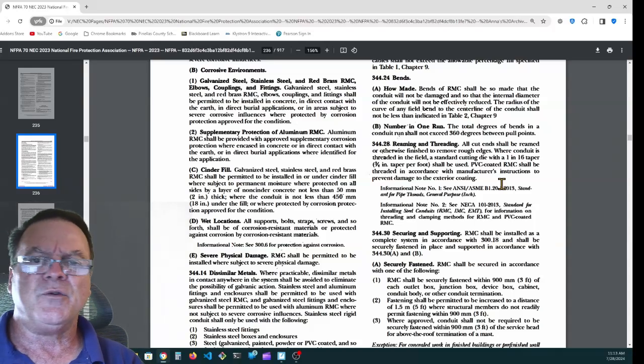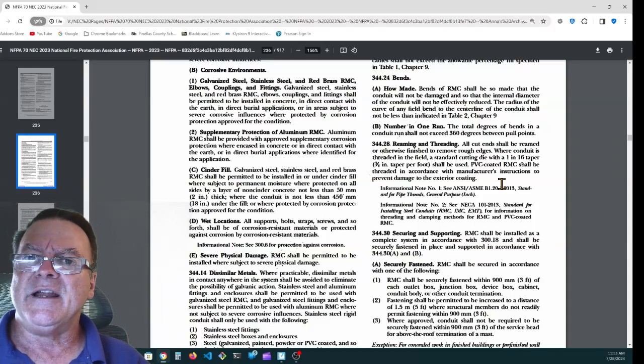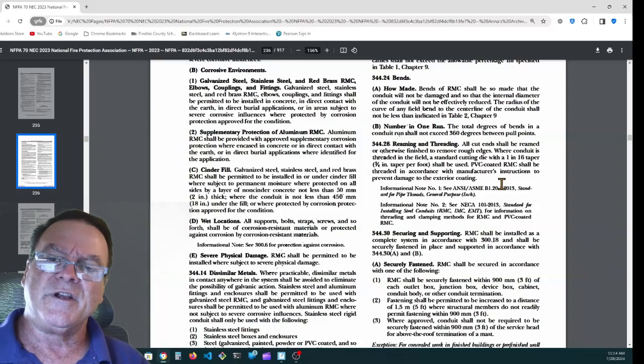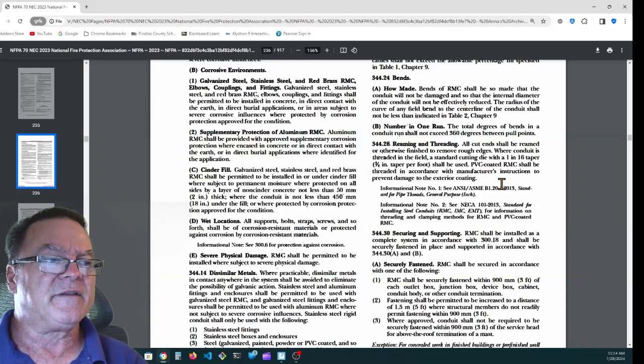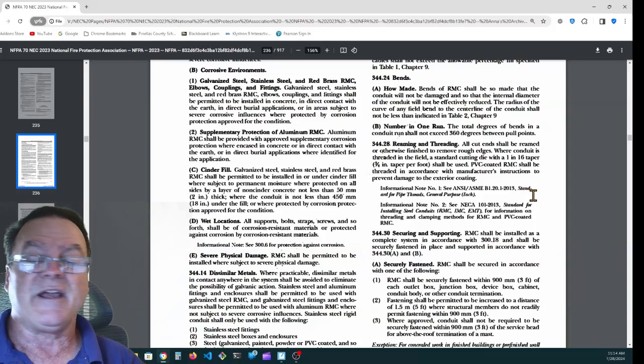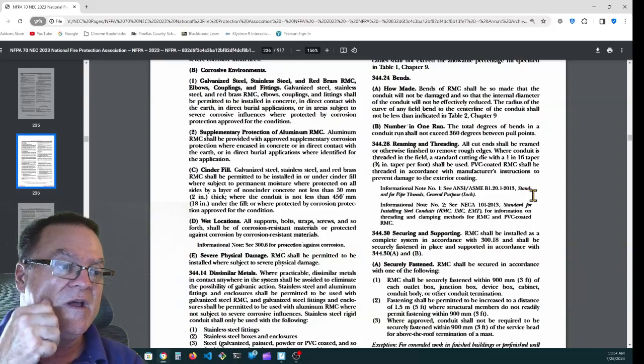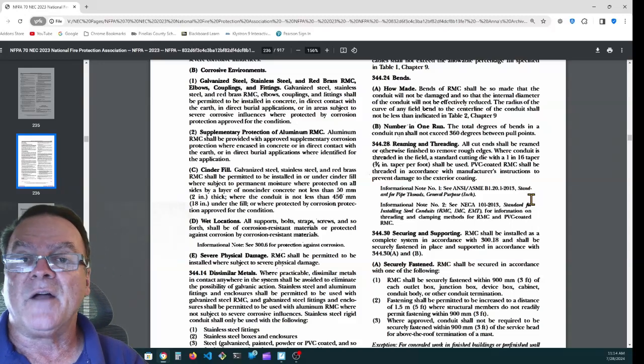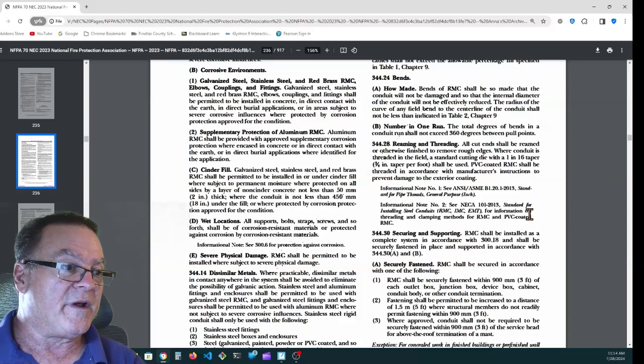This happens a lot if you have it lying out in the sun and it gets particularly soft. When you go to thread it, it'll just tear up that PVC coating. Then it has to be repaired or discarded. You can't use it that way. So it's best to just go ahead and cut that off with your pocket knife before you thread.